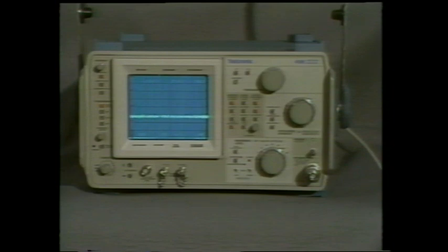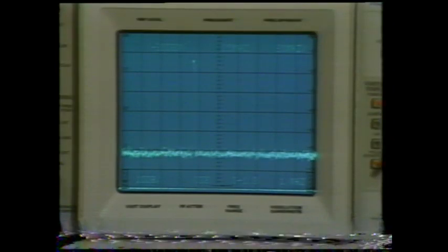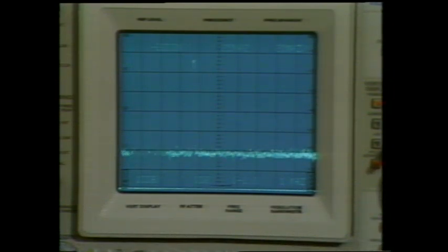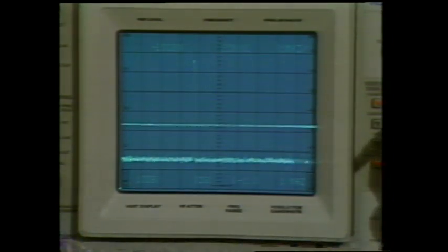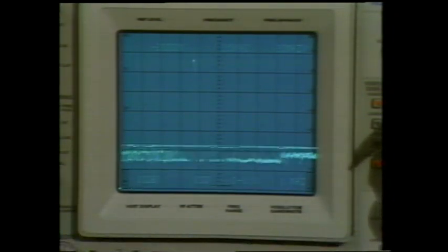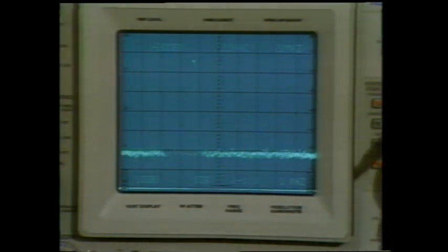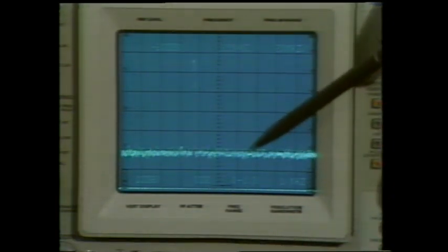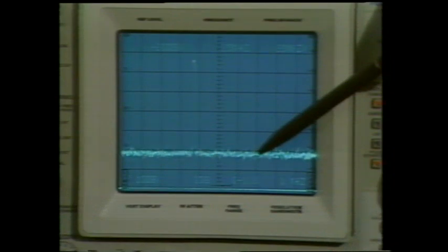The 496 is an excellent instrument for measuring impulsive signals. Spectrum analyzer sensitivity is specified as the average internal noise level, but impulsive signals must be peak detected, so we lose the peak to average dB difference, which is about 10 dB. At 1 megahertz resolution bandwidth, this corresponds to about minus 80 dBm peak signal sensitivity.